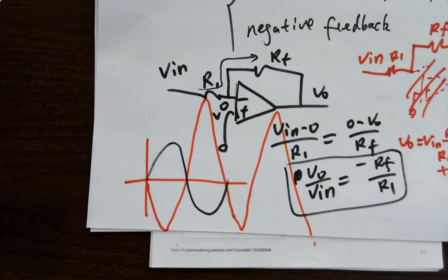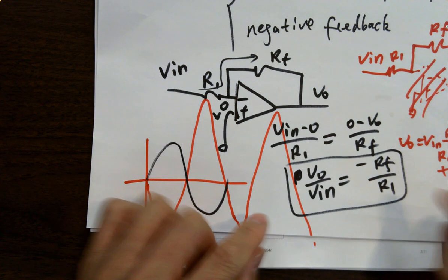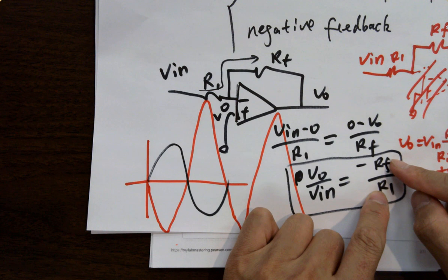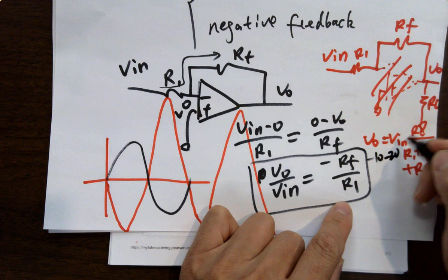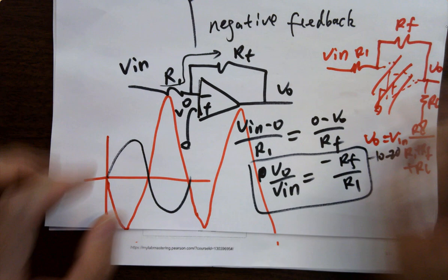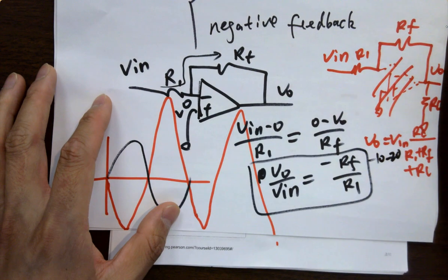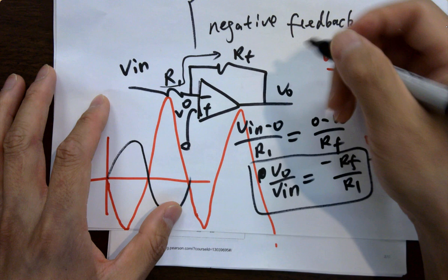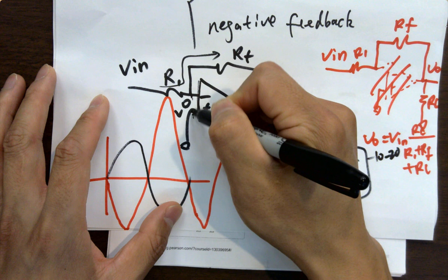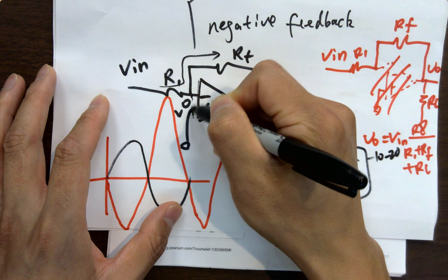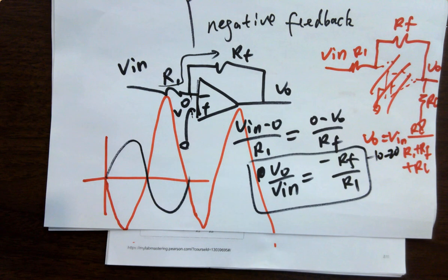How much does it amplify? You can define it by configuring the ratio of the two resistors. Usually 10 times to 20 times is ideal, but you don't want to do too much because the op-amps are not ideal. There's always a little, which means the inputs are not perfectly equal. So there will be a little offset, called DC offset, that is being amplified.